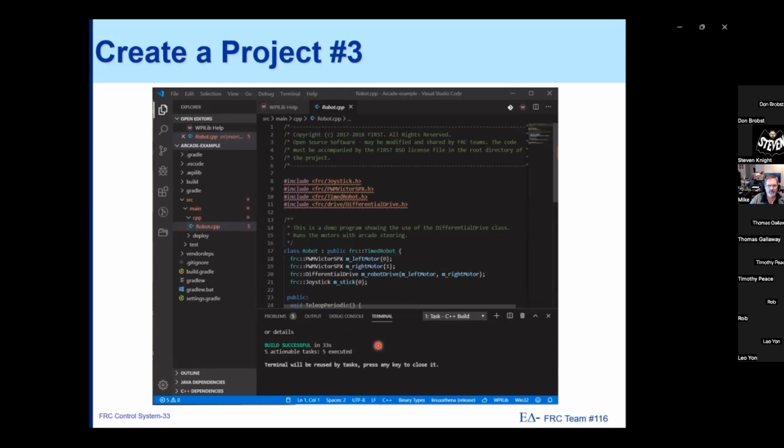I have seen that happen. Doesn't happen very often, but certainly can happen. So you'll want to make sure that this build successful shows up. Even though we see some examples that it shows problems, in this case it shows 5 problems, this happens to be because the search for these header files wasn't done correctly. If you then turn around and tell it to update the search path, then it will automatically solve these problems, and then the number of problems will go down to 0.